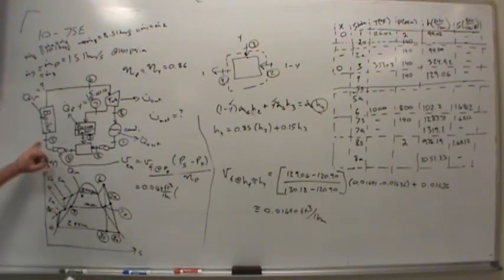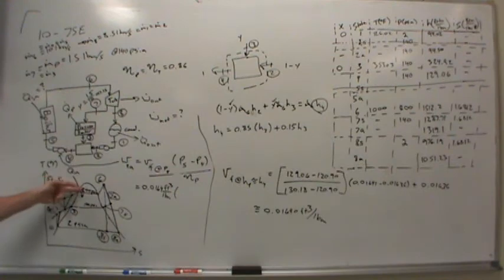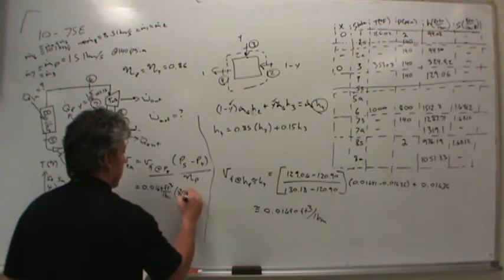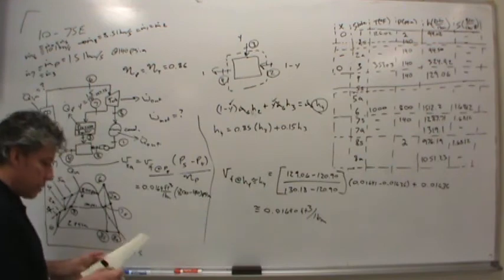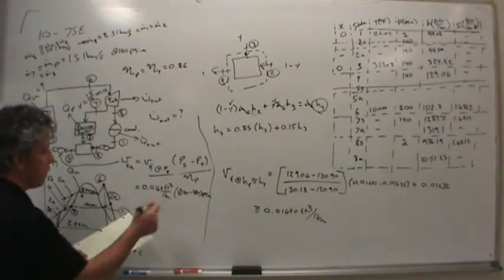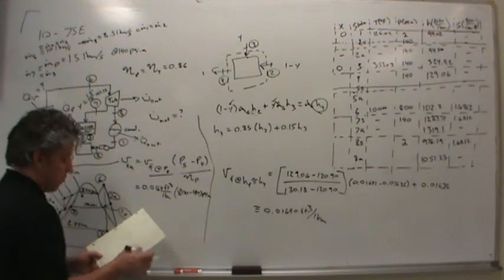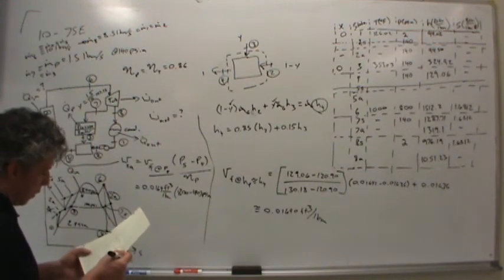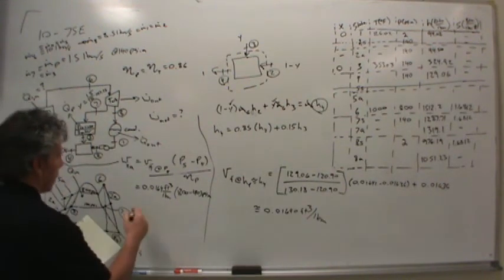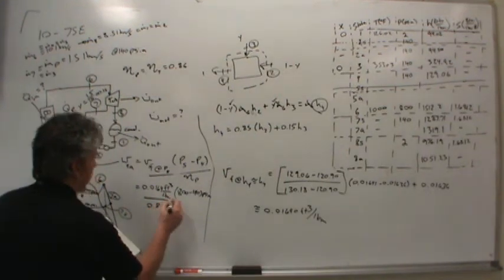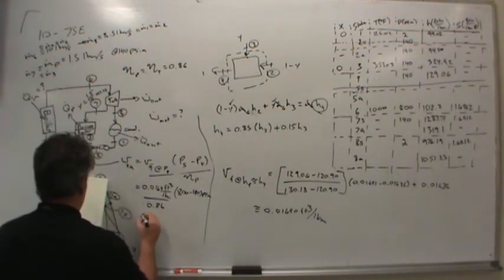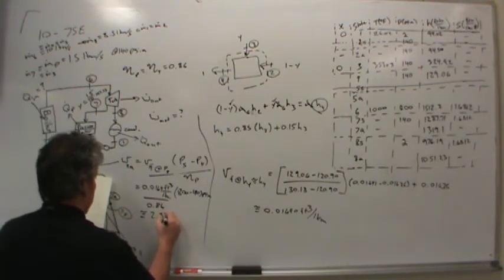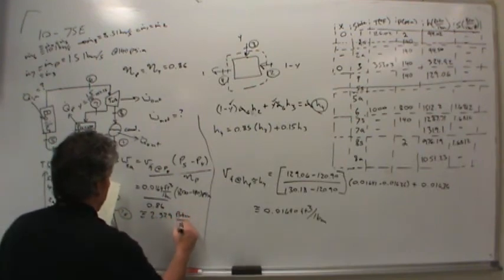Of course, the pressure change between state 5 and state 4 is 800 versus 140. So 800 less 140 PSIA. I used a conversion factor before. Understand I would have to use it again to go from PSIA cubic foot to BTUs, but I will just show you the result. Oh, let me not forget to divide by the isentropic efficiency of the pump. Okay. But anyway, you end up with a pump work of about 2.329 BTUs per pound mass once all the conversions are done.